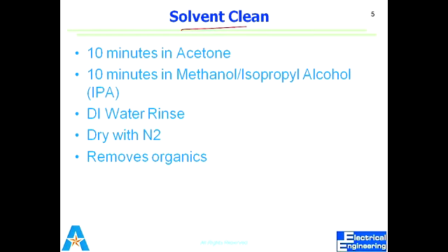If somebody among you has been working with functionalizing the surface, meaning you are working with maybe DNA or RNA or some other things like that, in that case you have observed that for the cleaning process, you follow this protocol. You spray acetone, then you spray IPA, and then DI water. Mostly you repeat this process 2 to 3 times, so that you make sure that the surface is clean and you have not damaged anything. So they are not very highly reactive chemicals that we are using. It's just an example of organic cleanup in back end of line process.